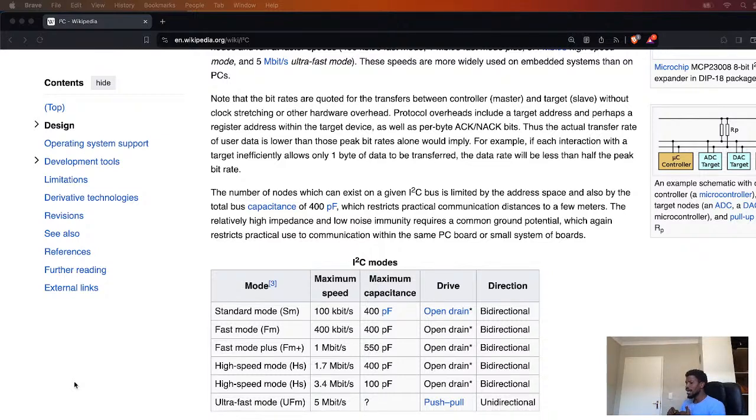In SPI we were using a slave select line, NSS, to select which slave we wanted to communicate with. However, with I2C we have the capability of using addresses. So we have a 7-bit address, and it is an 8-bit packet, where the address is 7 bits, and then you have a read or write bit at the end.